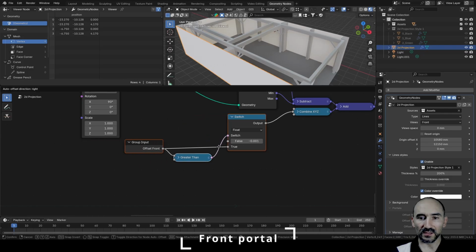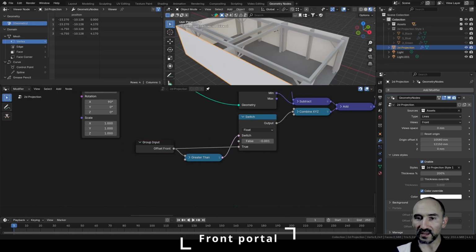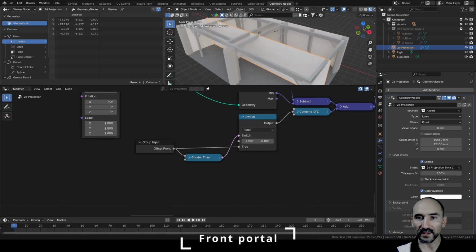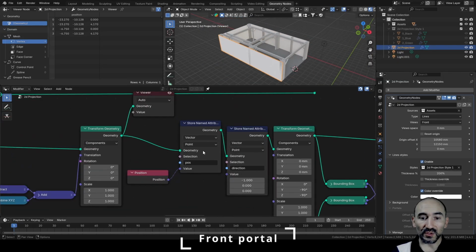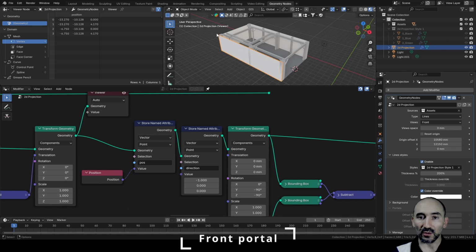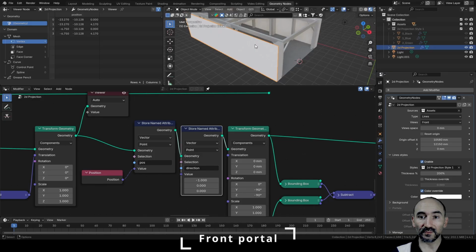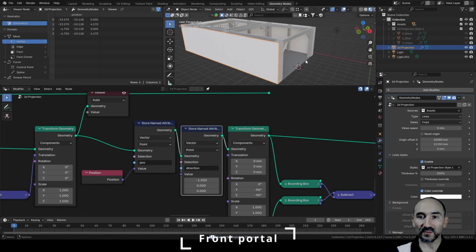I can move this node a little bit, and now if I increase this offset I have the correct shifting inside this collection of assets. Next we want to save the position. Okay, it's correct, as you can see here. Next we want to save the direction that is wrong in this moment, because the looking I want to have from this rectangle is the positive y-axis, so this direction. So I need to set not -1 here but 1 in the y-axis for this direction attribute.